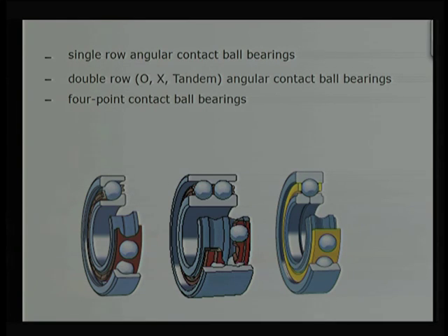We discussed something about the deep groove ball bearing, that it gives a good positional accuracy and is a cheap one. It is a low cost, readily available in the market. However, there are some other bearings also, having some more contact angle, and we are trying to show how other bearings are better than the deep groove ball bearing when there is an axial load.